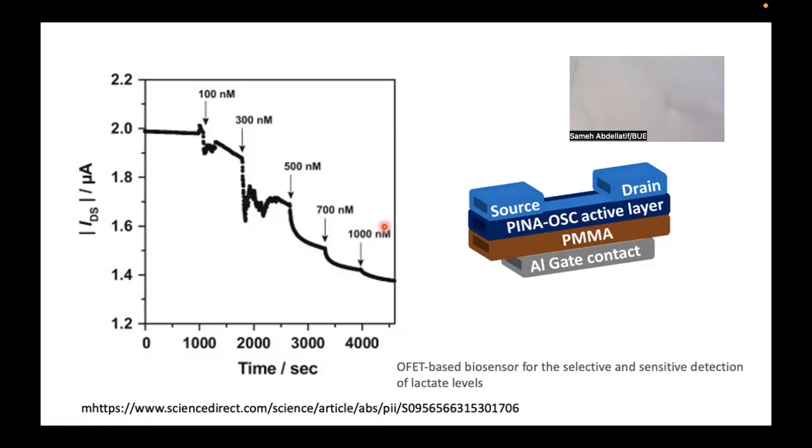So in order to prepare your data to be compatible for an ADC conversion, you have to convert such a change in current into a corresponding change in voltage corresponding to the expected voltage dynamic range in the ADC. For example, if your ADC is working from 0 to 15 volts, then you are expecting to convert this variation in current into a variation in voltage in the range of 0 to 15 or whatever.